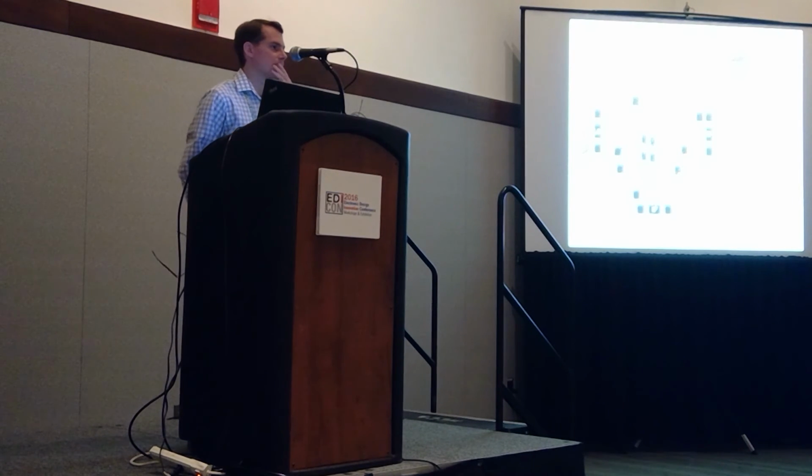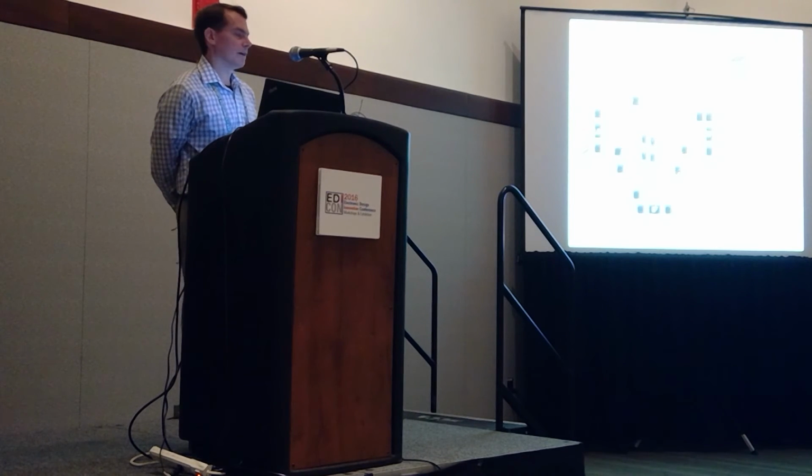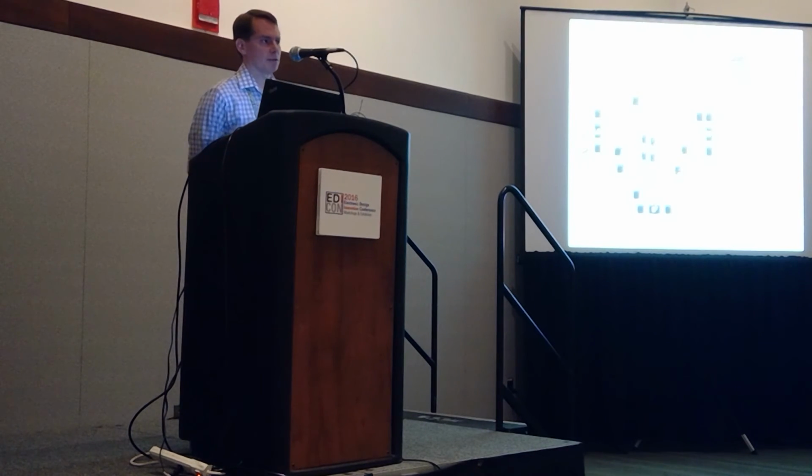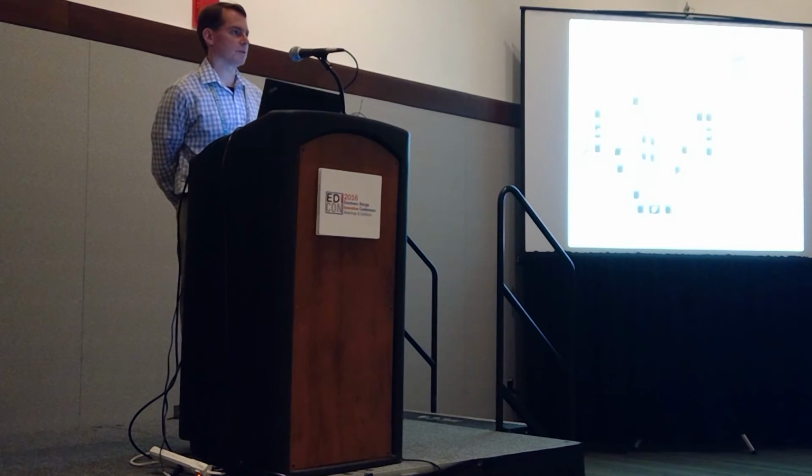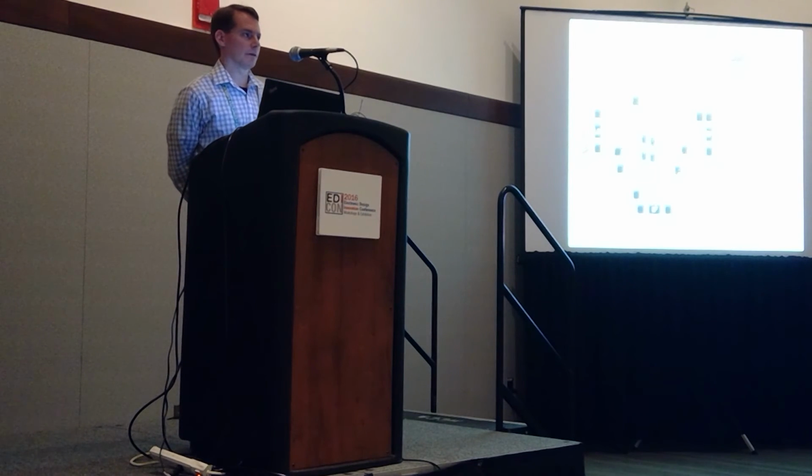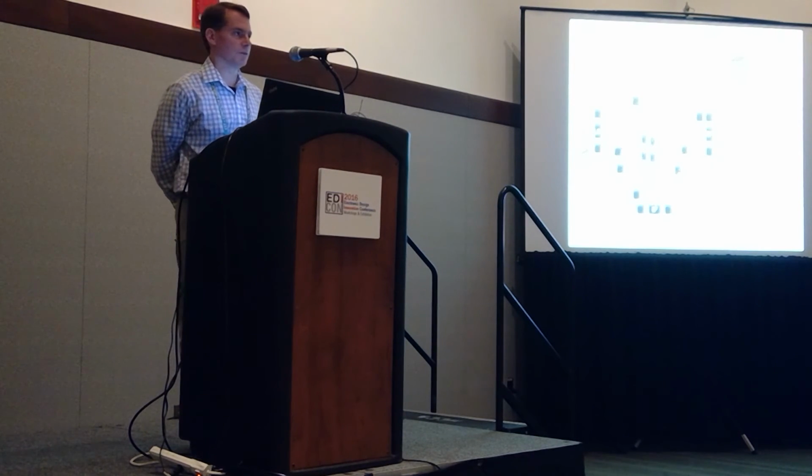What type of packages are you using? These are what we're looking at right now, the kind of air cavity ceramic package, the Colorado Microcircuits style. I believe you can also, especially the S-band one, put in plastic, but for some of the higher frequency ones, we like that air cavity package much better.